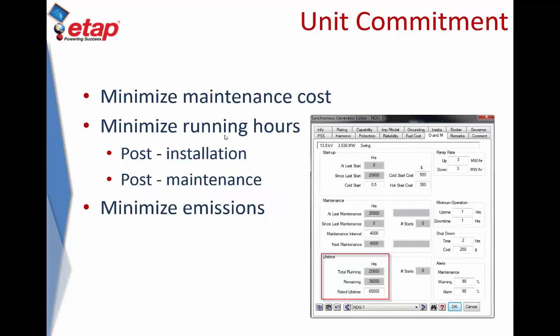So as far as frequency control and economic dispatch is concerned, that's straightforward. One's dealing with frequency. The second one is dealing with cost and losses in the system. And then when we deal with unit commitment for microgrids, we're actually dealing with starting and stopping generators based on these objectives. The unit commitment in a traditional sense in a utility is quite different, because that actually relies on day ahead forecast. This unit commitment actually relies on a much shorter term, a shorter horizon forecast. So we are able to actually run this on a few second to few minute basis, because in case of renewable energy, the wind and solar output can dramatically change in a matter of seconds to minutes, depending on the situation.